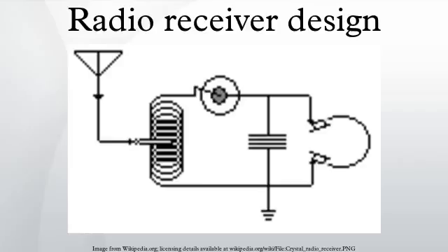Direct conversion. In the direct conversion receiver, the signals from the antenna are only tuned by a single tuned circuit before entering a mixer where they are mixed with a signal from a local oscillator which is tuned to the carrier wave frequency of the transmitted signal. The output of this mixer is thus audio frequency, which is passed through a low-pass filter into an audio amplifier which may drive a speaker.